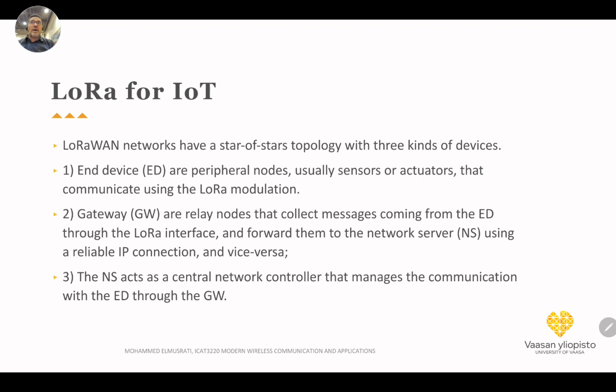One of the discussions going on now is using cognitive radios. We talked about cognitive radios as an emerging technology, where LoRa might in the future just sense if there is a free space or white space, even in a licensed band. For example, 5G uses some licensed band, but if that frequency is not used in a certain area, why not let LoRa use that band, taking into account that it will not cause any harmful interference with 5G?